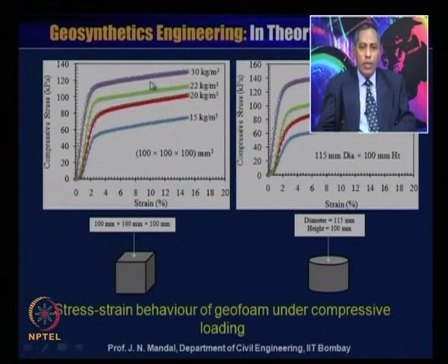You can see that under all the different densities, the nature of the curve is similar, and it has also been noted that with increasing density of the expanded polystyrene geofoam, the compressive stress also increases. So, when you perform the test on a cubical specimen of 100 by 100 millimeter, you can observe the nature of the curve, and it is also noted that as density increases, the compressive strength of geofoam also increases.